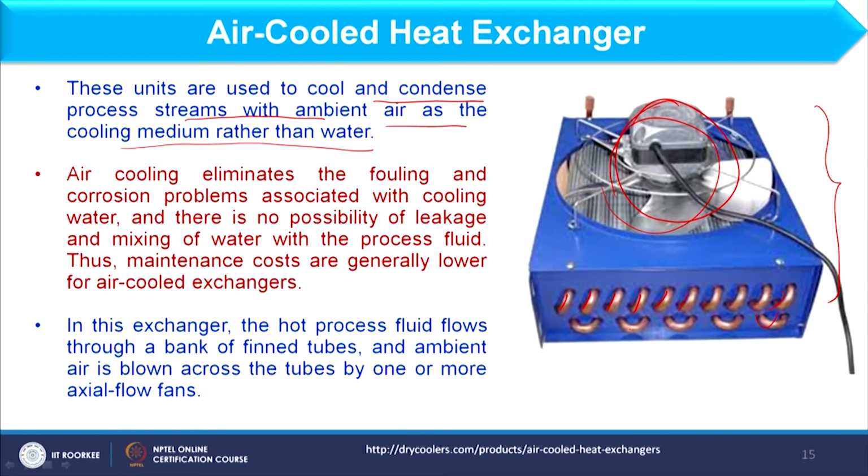Okay. So in this air cooled heat exchanger, if I am putting the fan at the top, that is before the process is going on, because once air is thrown by this fan, then condensation will take place. This type of placement of fan we call an FD fan or forced draft fan, because it forces the air into the system. It means it creates positive pressure in the system.